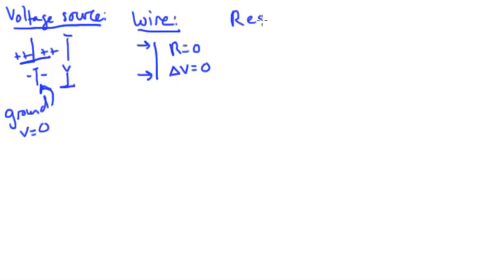Next element that you are familiar with is a resistor. So a resistor is this little zigzaggy thing. It has a quantity called resistance, usually signified by R, that just describes how hard it is for current to flow through this element, and what happens by providing friction is energy gets dissipated into the environment. So we'll have some current I that flows through it, and now the voltage across this element, so we'll call that V sub R, is equal to I times R.